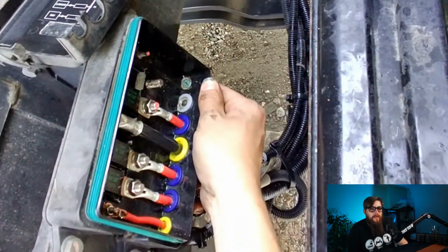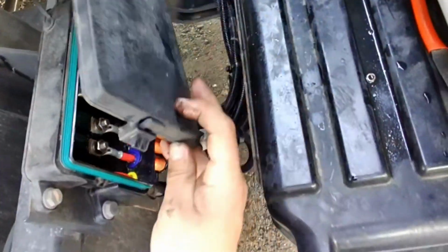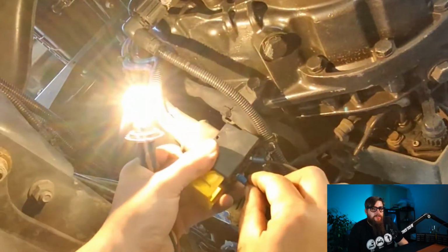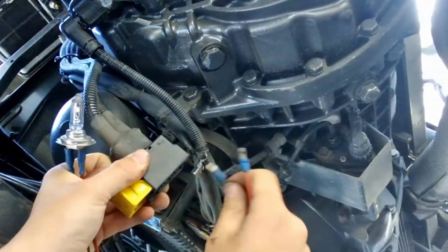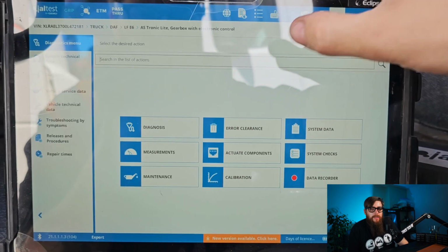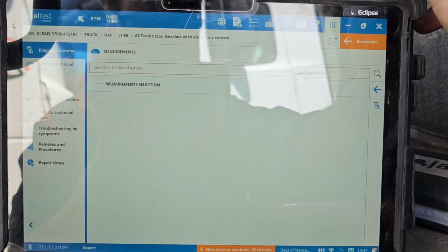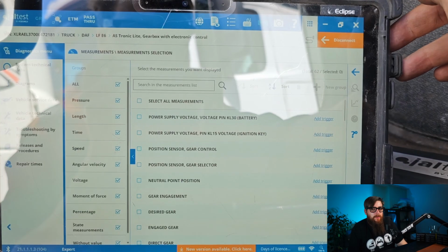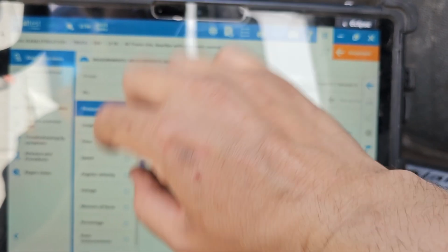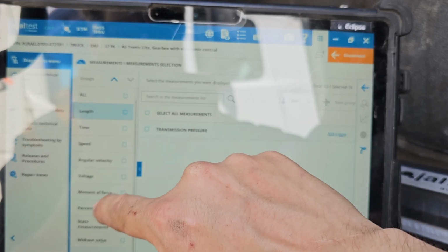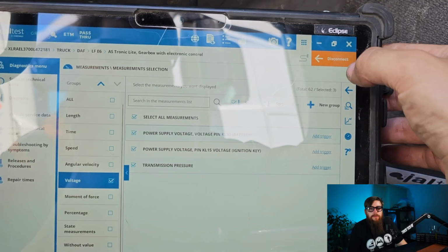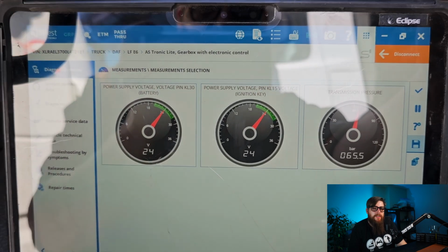And with the rubber blank now in the other end, we can close this up and see if we've got our diagnostic and rectification correct. Just plug this power supply back in here and jump onto Jaltest. We can connect back to the power pack and select our pressures and volts again. Stable voltage and a correct pressure reading always helps.